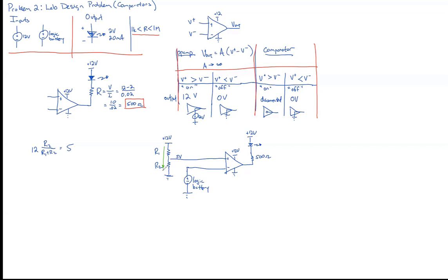Let's keep it to, say, arbitrarily 1 milliamp. And so our 12 volts over R1 plus R2 equals 1 milliamp. And then let's see how that works. If these R's are in this range, it works. And if the R's are way too big, then we'll adjust this number bigger or smaller until the R's get in the range. This is a perfectly good approach. I'm going to rewrite this a little bit more clearly. My handwriting gave out there. R1 plus R2. Now it's clear.